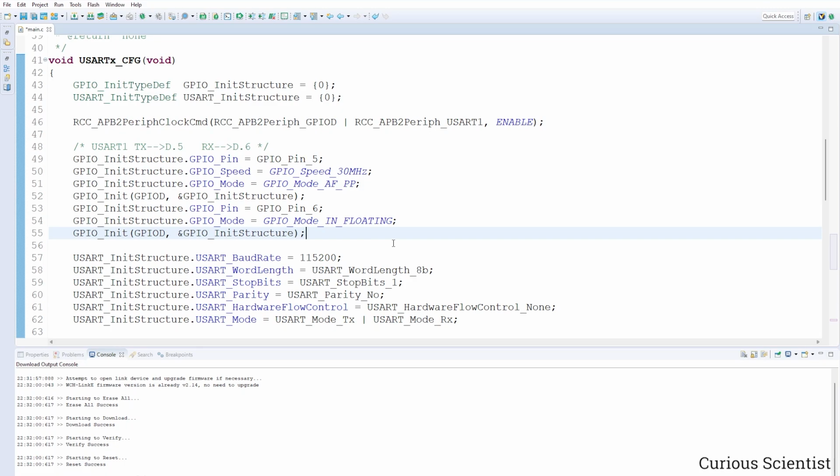So if we remember from the previous example, then the LEDs were located on the GPIO-D port mostly. So PD0, PD2 and PD3 pins, that's still the same. And then there was another LED on PC1.